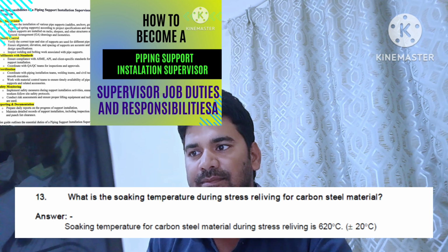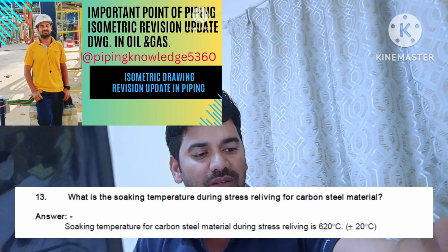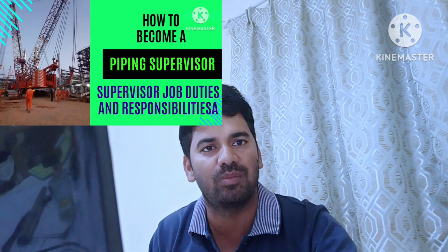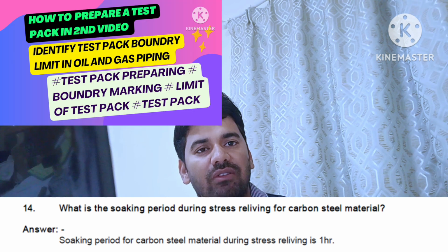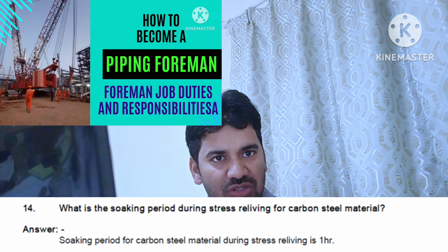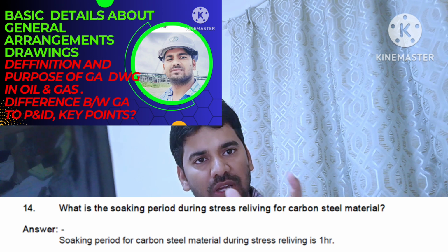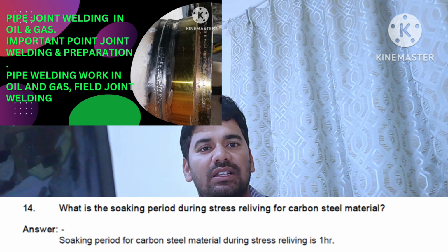The next question is: what is the soaking temperature during stress relieving of carbon steel material? During stress relieving of carbon steel pipe, the soaking temperature is 620 degrees Celsius plus or minus 20. What is the soaking period during stress relieving of carbon steel pipe? The soaking temperature is 620, but the soaking period is 1 hour. So the soaking period of carbon steel pipe during stress relieving is 1 hour.